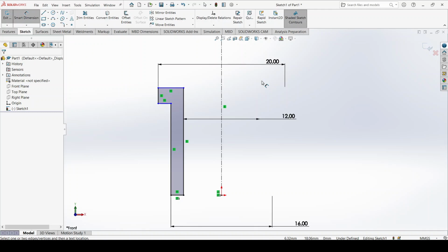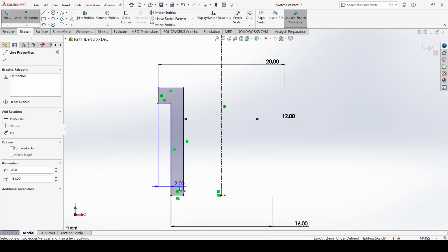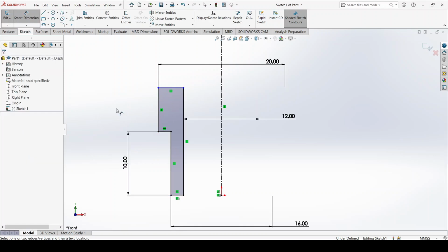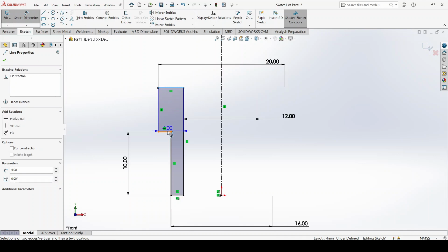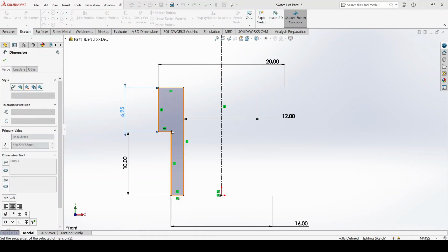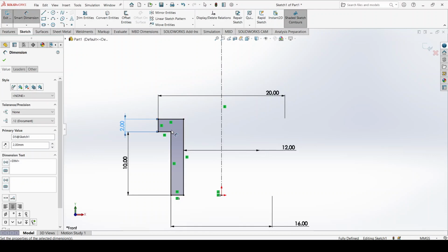And let's go, we have a value of 10 in this direction. And it's supposed to be 12 overall, but I will just add this one. And as you can see, I'm always clicking line to line. Why do I do this? I think this is best practice since it gives me a confirmation these lines are parallel to each other.